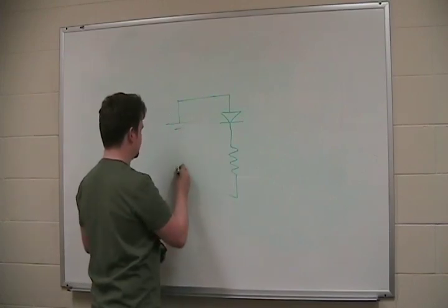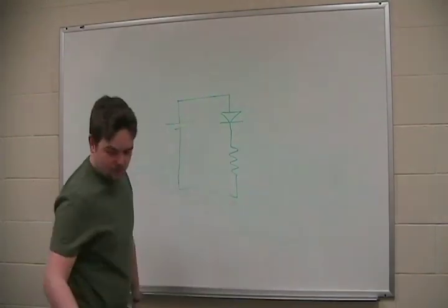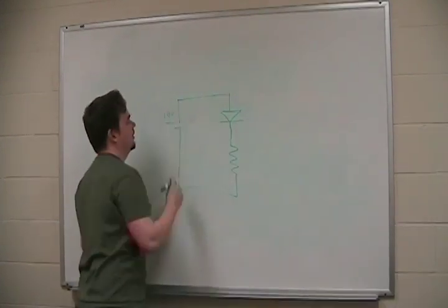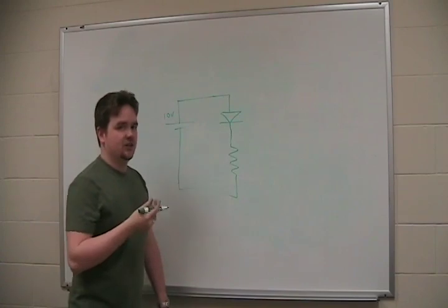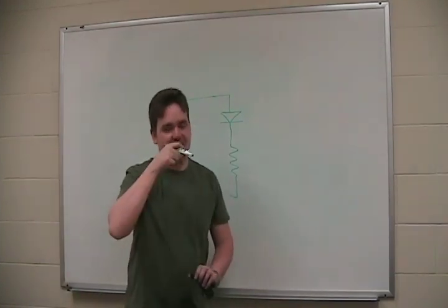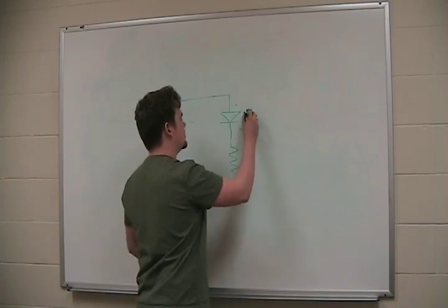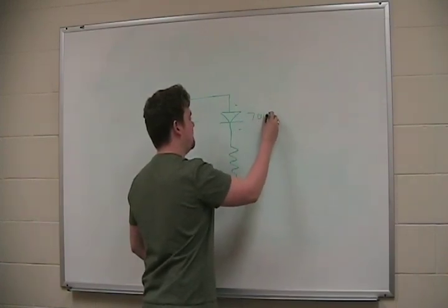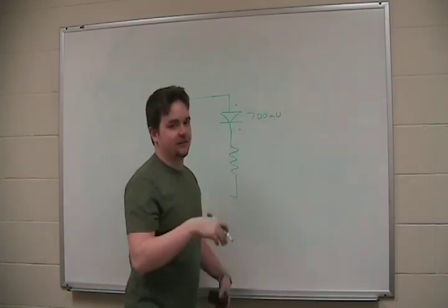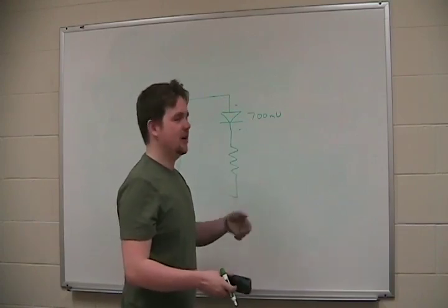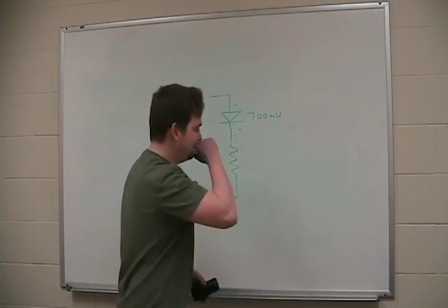So, one of the interesting things about a diode is when it conducts electricity, you have to have at least 0.7 volts, so 700 millivolts. So there will always be a 700 millivolt drop when it's conducting fully. Now it might be a little bit less, between 500 and 700, but in school they teach you roughly 700 millivolt drop.